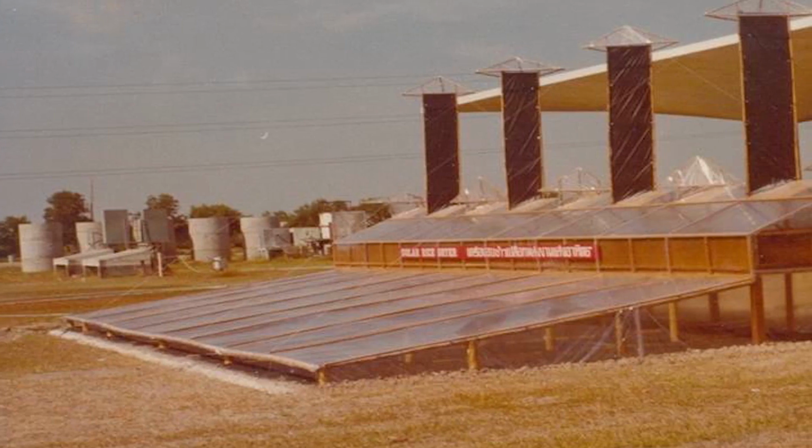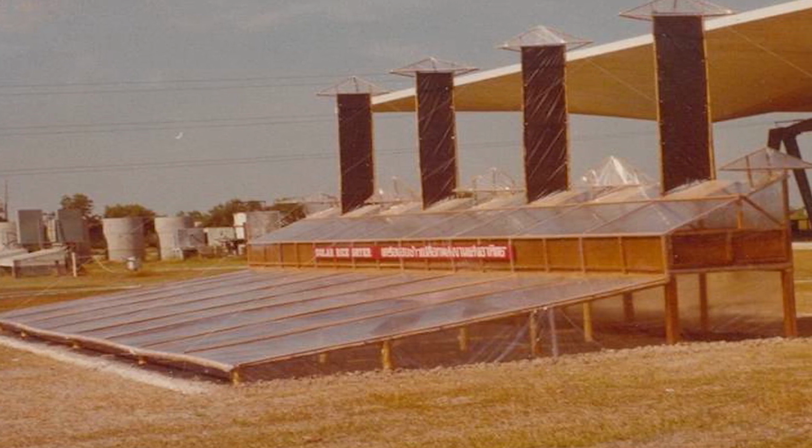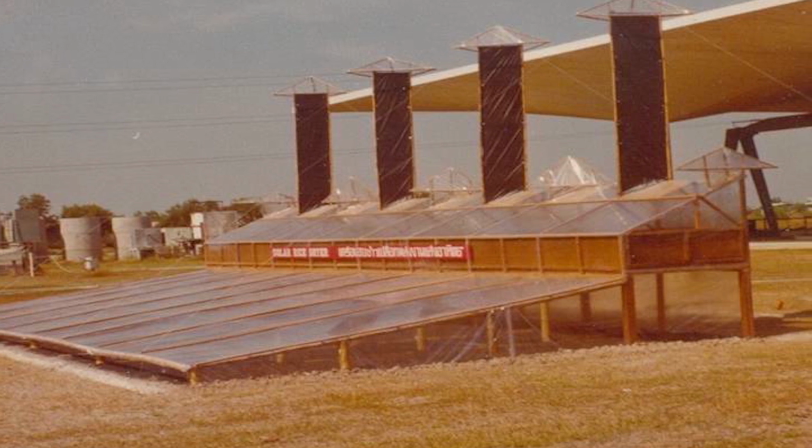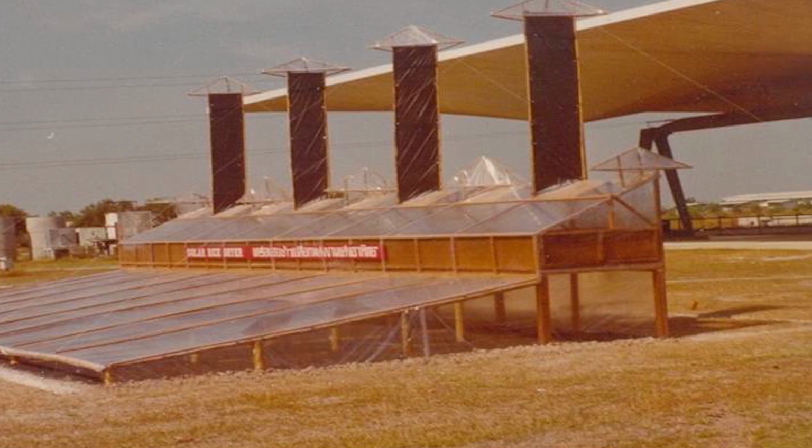By doing so, we reduce the moisture content of the material, and then we can preserve it for a longer duration. In our Indian climate and in many other countries, we have to preserve food grains, vegetables and fruits for a longer time, and that is the reason we dry them. We reduce the moisture content from around 60% to 15% through the drying arrangement, and at about 15% moisture content we can preserve the material for a longer duration. So this is the purpose of drying.